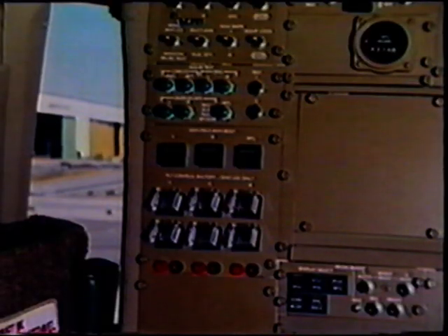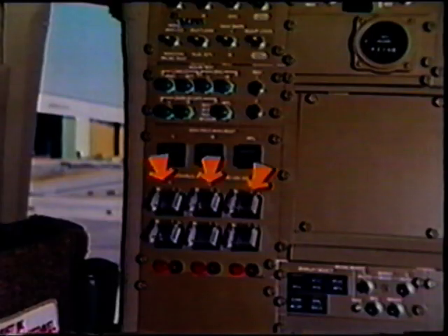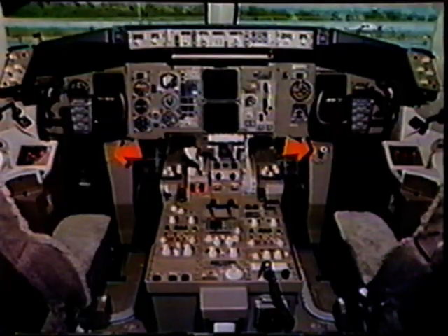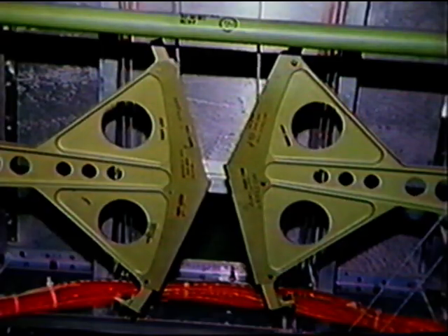Positioned on the left side of the P61 panel are the flight control shutoff valve switches and indicator lights. The amber rudder ratio light is located on the P5 overhead panel. Rudder pedal adjustment cranks are forward of the captain's and first officer's seats. Located below the flight compartment in the forward equipment center are the captain's and first officer's forward rudder quadrants and rudder pedal steering mechanism. These are accessed by the crawlways through the main equipment center.